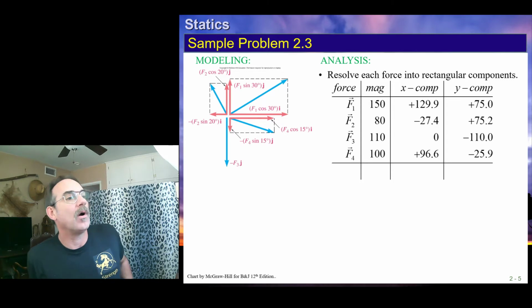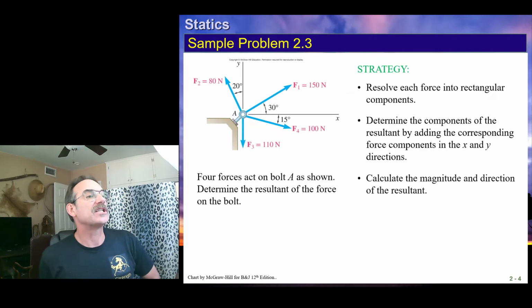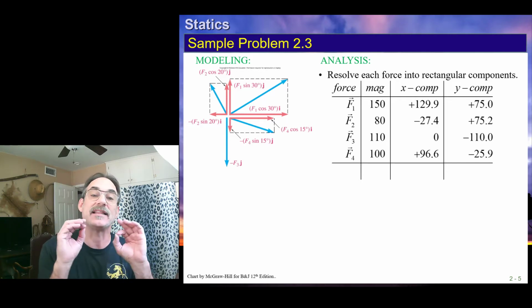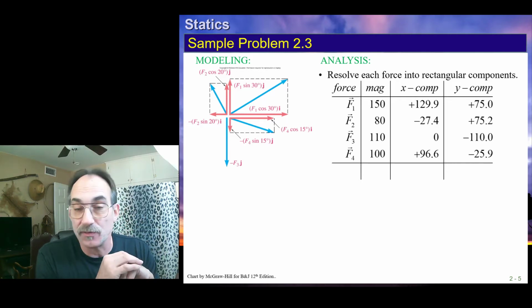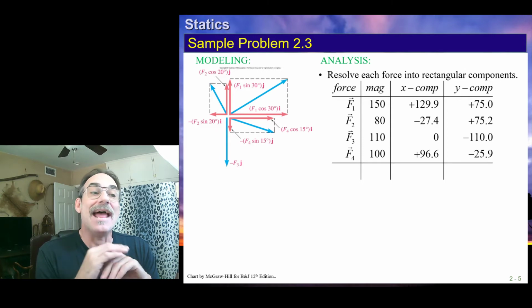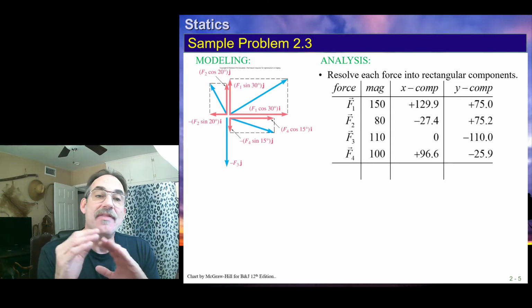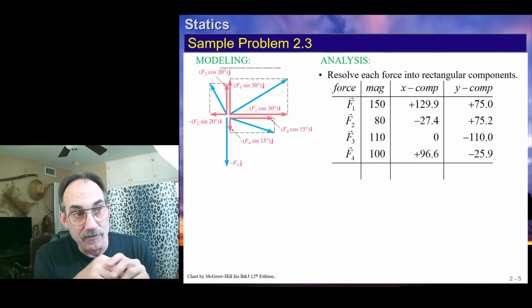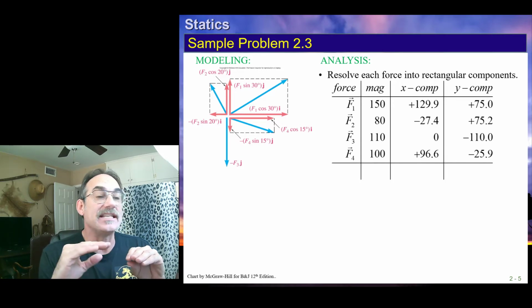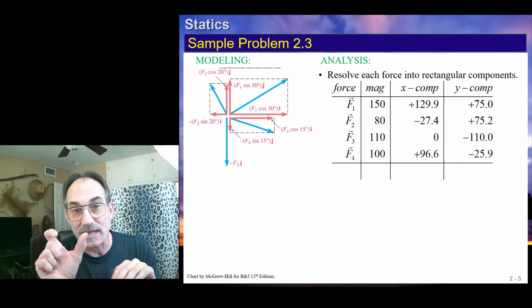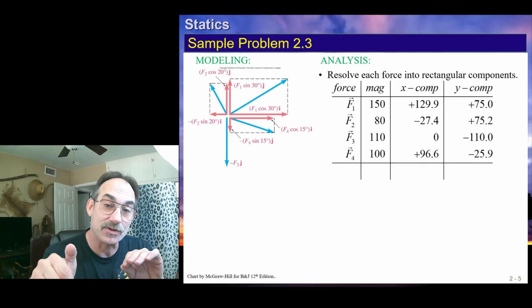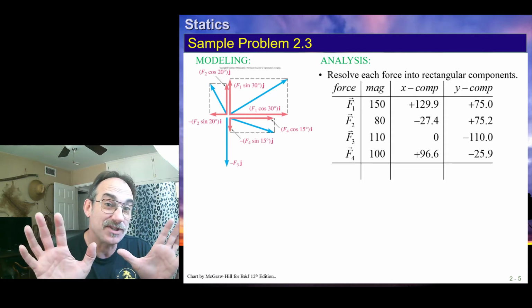And then our vector 4, which makes an angle of, it looks like negative 15 degrees. If you plug in negative 15 degrees, take the cosine of that times the magnitude of the resultant, that's your x component. And then the sine of that times the resultant will give you the other component. Or you can just say it's a 15-degree angle and recognize that that's a positive for the horizontal and a negative for the vertical, since that component is going to be acting downward. Once again, we're talking equivalent forces.